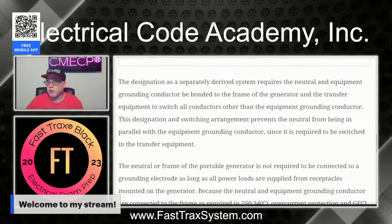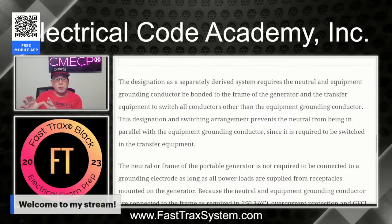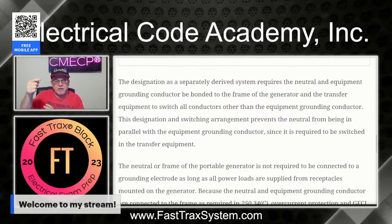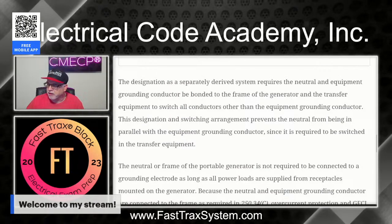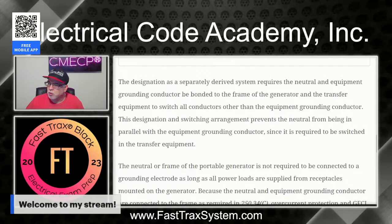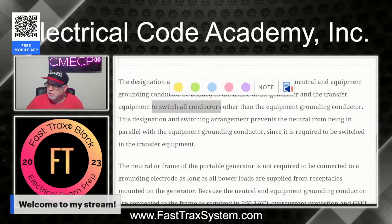Now, let's read a little further. It says, the designation as a separately derived system, so that's what a portable generator is with the bonding jumper on it. So we're having it from the neutral point over to the frame. That would be standalone. That's a separately derived system. It requires a neutral and equipment grounding conductor to be bonded to the frame of the generator. We all agree. And the transfer equipment to switch all conductors